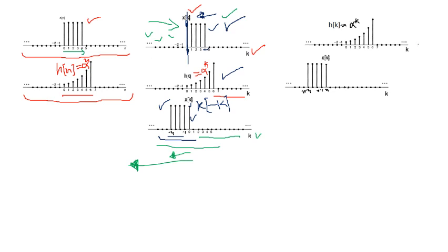So if I plot the two signals, now you can easily observe that this is your response signal, which exists again from 0 up to 6 as it was, because we haven't done any operation here, but we have performed the operation of reflection and shifting on this signal. Now this is your x of n minus k.